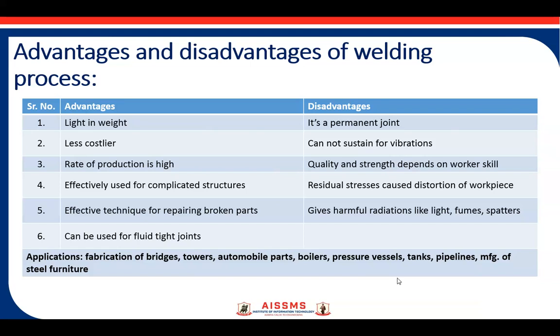The disadvantages of the welding process are: it forms a permanent joint. It cannot sustain vibrations, that is, high frequency vibrations. Quality and the strength depend upon the skill of the welder. Residual stresses cause distortion of the workpiece. It gives harmful radiations like light, fumes, spatters, etc.